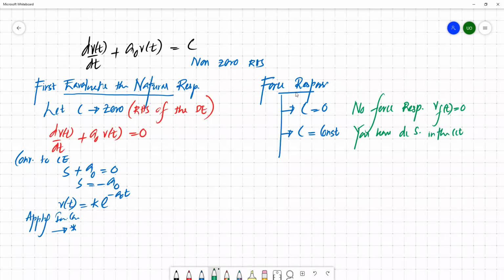If your right hand side is a constant, like in the example we discussed just before, it's like I naught divided by C. I naught is the value of the DC current source, C is the capacitor. So this is basically a constant. So we know that the circuit contains DC sources. We had this DC current source of I naught. If your right hand side ended up with a constant, it basically contains DC sources.